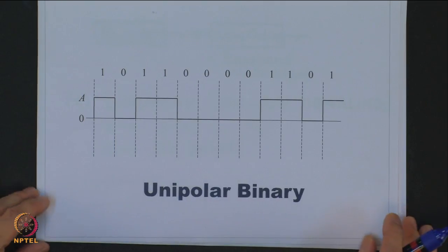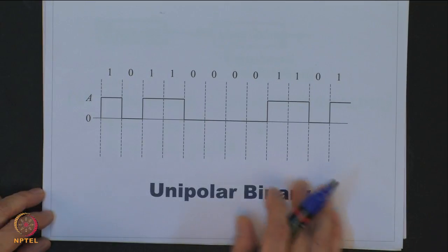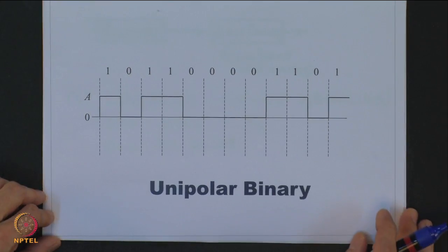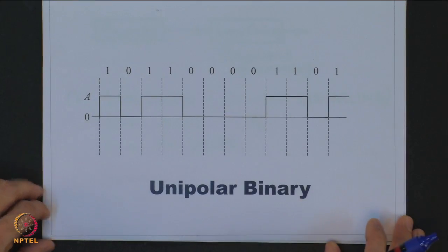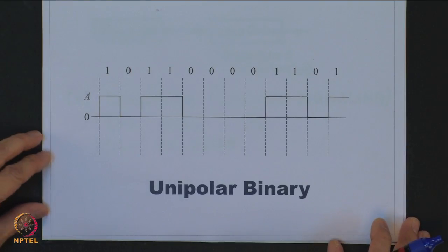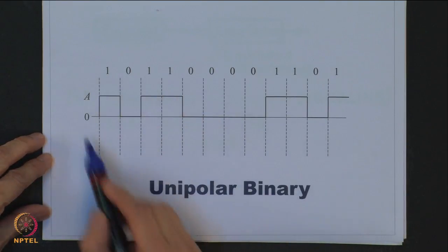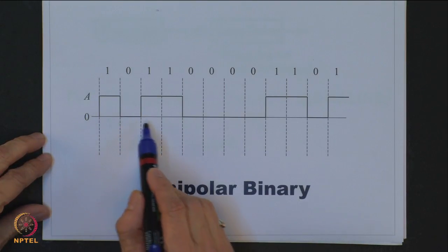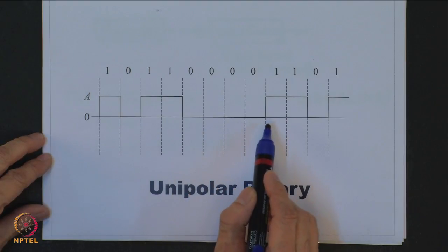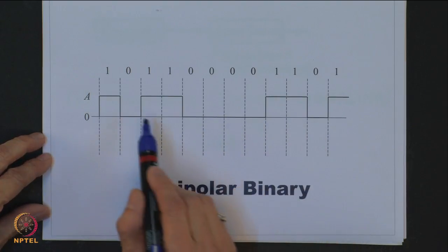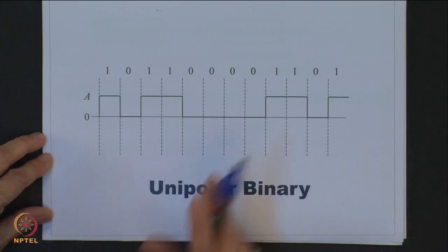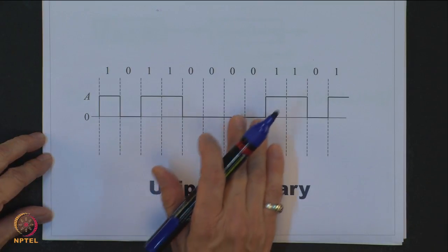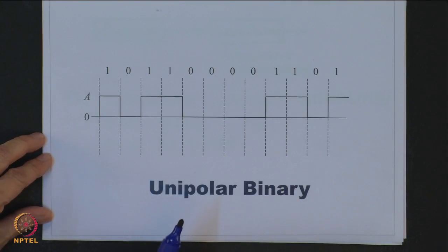Now, we will see soon that these line codes should satisfy certain properties for the transmission over the channel. Now, if you look at this line code, unipolar code, here if you have continuous zeros, then this could create a problem, or if you have continuous 1s, this could create a problem later on, and that is the problem of what is known as synchronization, correct.